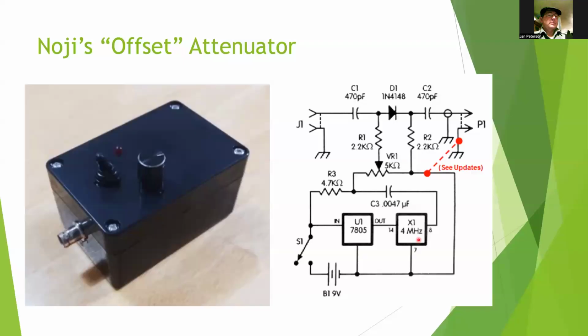Okay. And remember, since you're just receiving, it doesn't matter if you're outside the band when you do that, which you will be. But since you're only receiving, you don't want to transmit through one of these things or you'll ruin it. But you can set this up so that you can actually tune into that a little bit off from the Fox. And then if you get out to where you're finding, oh, geez, I can't find my Fox anymore, just switch back to the main frequency.